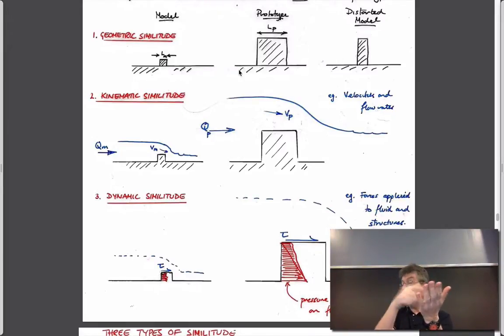to turbulent flow, where now all of a sudden it's no longer parallel and planar relative to each other. As you make the transition to higher Reynolds number, just like in a golf ball, which has dimples on it to be able to set up turbulence because it can travel through the air more efficiently, in pipes it's the small scale roughness on the walls of the pipe which heralds that transition from laminar flow to turbulent flow as the velocity increases. So clearly, if we're doing scale models of this, we have to also incorporate that roughness, which we'll find out. So geometric similitude has to be honored as the first requirement.